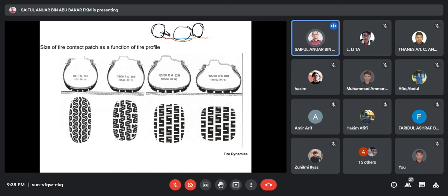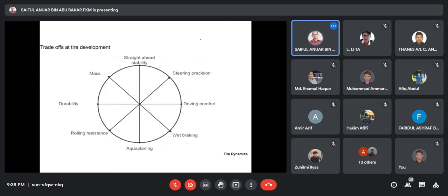So it's going to spin the wheels at very high speed. Okay, faster than you intended your car to go. So this one also can cause an accident. So if there is another car in front of you, for sure there is going to be an accident. So for safety concern, usually we don't turn on the auto cruise function or adaptive cruise function during raining conditions, or if there are a lot of potholes filled with water on the road. Okay, so this is some summary for the aquaplaning for tire.